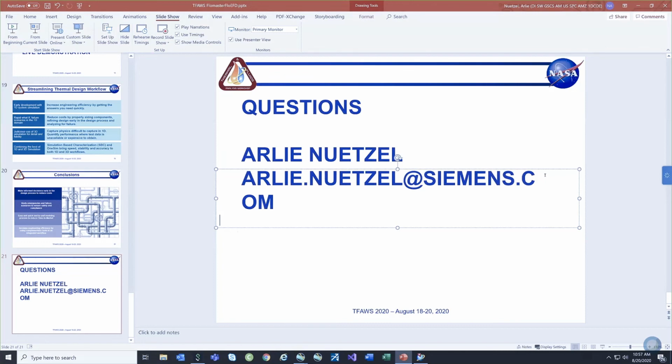Those are all excellent applications for AMESIM. Now, AMESIM is a transient tool, which means some of the things you might want to do in a fluid system model, like a quick steady state analysis, or flow balancing like I showed today in that first example, are a little bit more cumbersome to do in a tool like AMESIM. They're not impossible, you can absolutely do them, but they're a little bit more cumbersome.